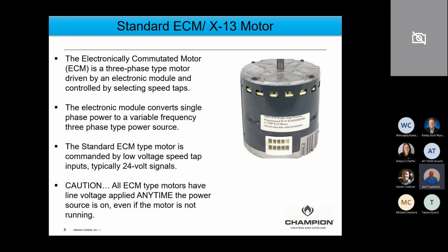It doesn't care what it's going to do. It's designed so that if you have multiple speed commands on it, it's just going to automatically take the highest command that it's getting. So unlike a PSC blower, where you'll burn the motor up if you have more than one speed command to it, these ECM motors could care less.